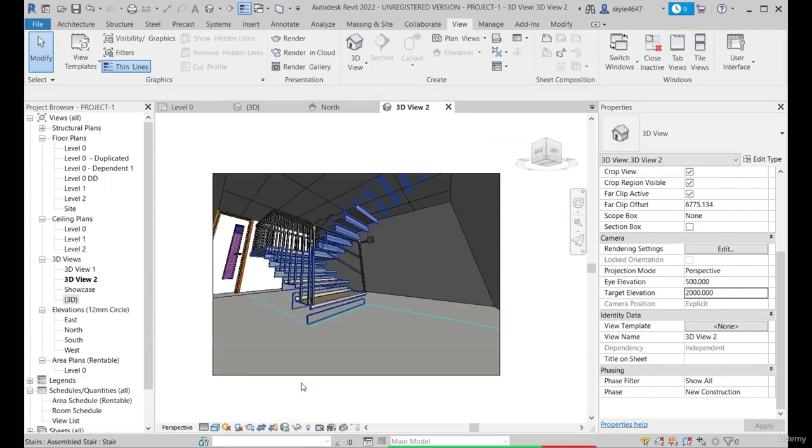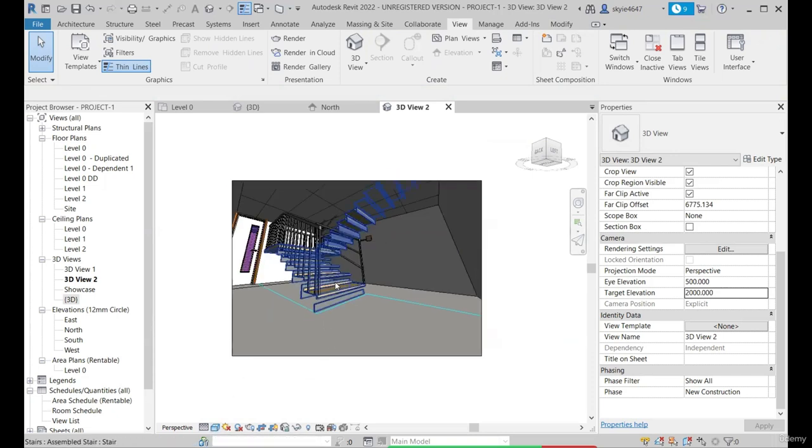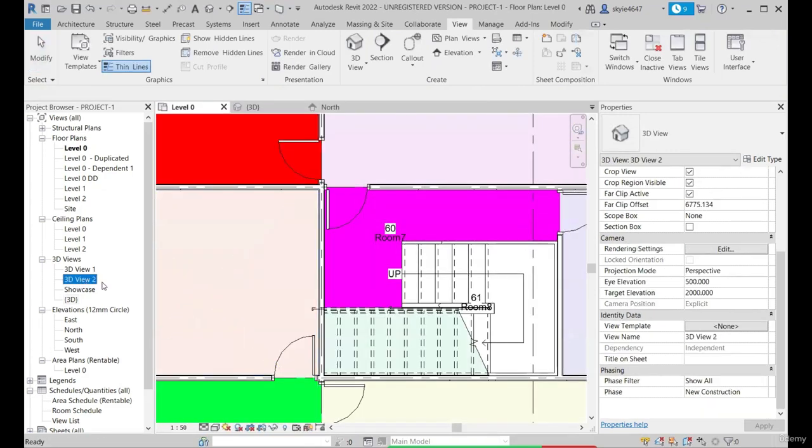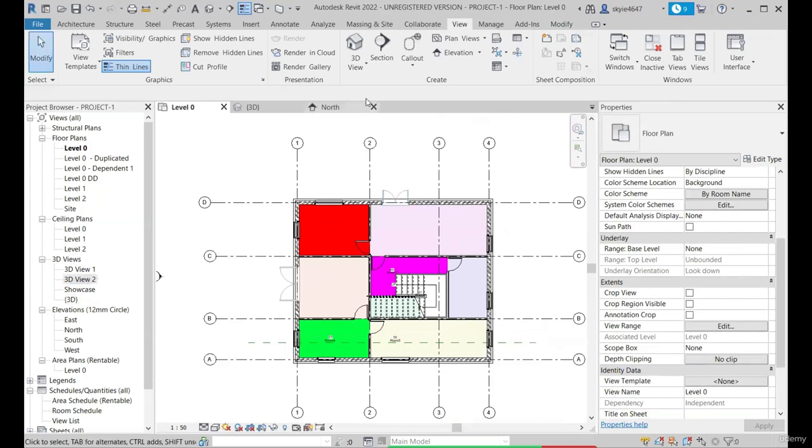camera tool. You can even change the detail level or the visual styles and all this stuff, as we do similarly for a particular view. So in this way you can have a camera view placed. You can rename it as needed or keep it as view 2. So in this way you can adjust and manage the 3D views.